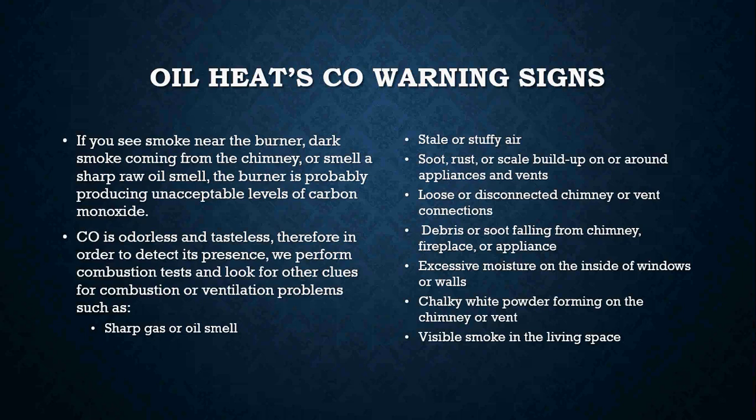Next time you're driving down the road, take a look at the chimneys. If you see black, grayish smoke coming out, that furnace is not working correctly, unless they have a fireplace going, which is completely different. But if it's a boiler and you see that sort of smoke, that's a sign that whatever is hooked up to that chimney isn't working right.